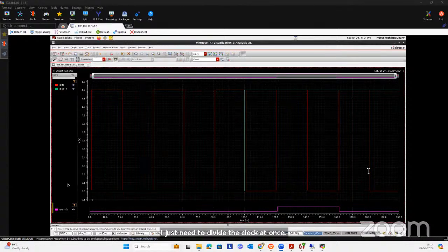Okay. So it's all design specifications: how we want to design, how we want to define, how we want to run, and all those things. So we have learned a few things in these tools. Using digital, we have done Verilog code verification using a digital test bench, and we have completed the full cycle of ASIC design flow. And second, using analog circuit design, we have imported digital Verilog code, that is a divide by 2 clock circuit.